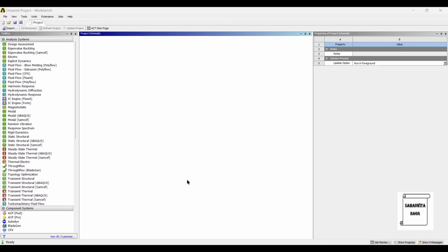The exhaust valves are primarily made of high heat resistant metals such as nichrome, silicon chromium or cobalt chromium alloys. For this analysis, I am choosing cobalt chromium alloy as the material. You can alternately study nichrome or silicon chromium as the material and analyze your valve.